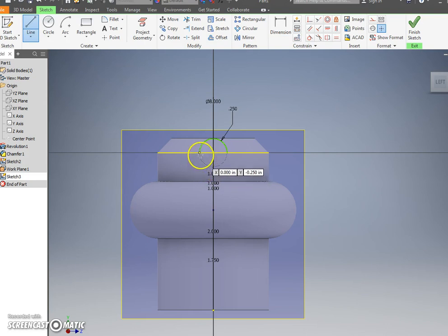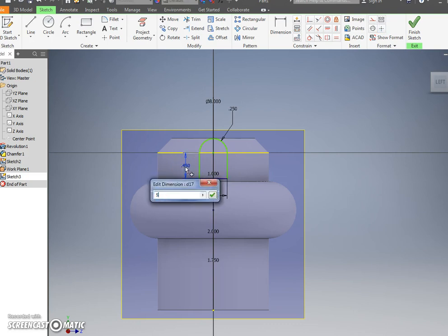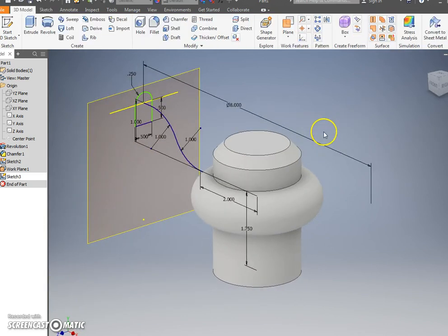Line, we need to draw a little box right here. So it's a simple box of, let me get on my other screen so I know what I'm talking about, there it is, 0.5, 0.5. Just a simple rectangle that's 0.5, 0.5, or square. So 0.5, oops, that's 0.45. I'll change it later. 0.5, and go up here. So I messed up on this one, but I'm going to change this back to 0.5. Wow, I cannot type today. There. Okay. Press finish sketch.